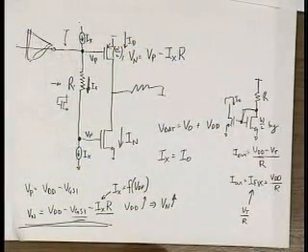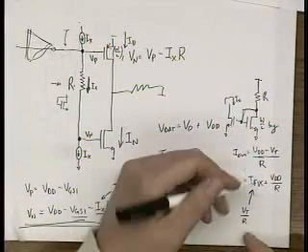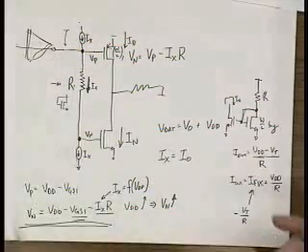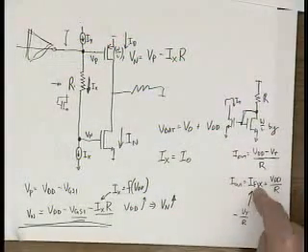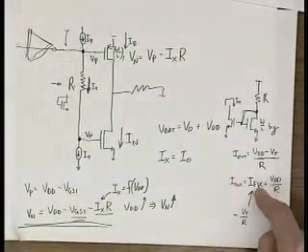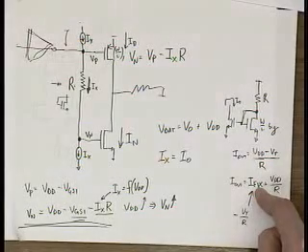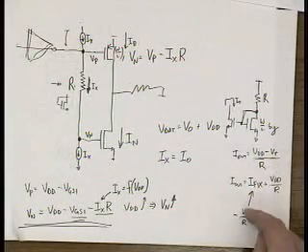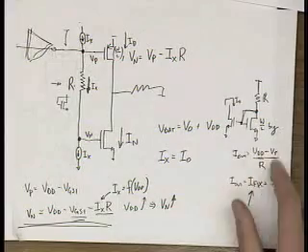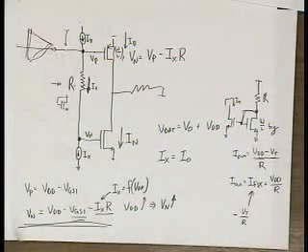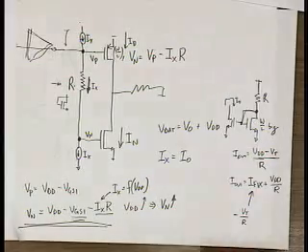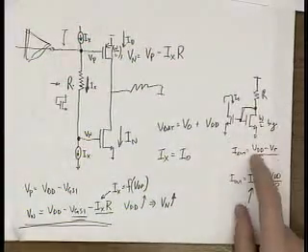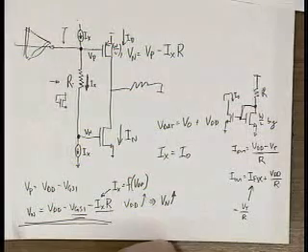Is that I fix? Yeah, I'm just calling it I fix, basically some current that is independent of supply. In this case, the fixed component is a negative current: minus VT over R. Now, in reality, you'll never actually get a negative current, because a condition for this to work is that VDD is greater than VT, right?